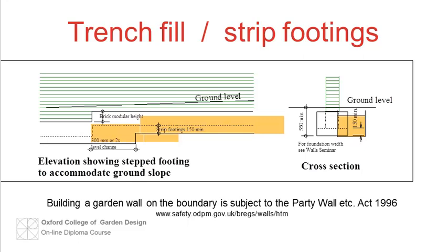The rule of thumb widths for concrete footings are given in the seminar on walls. Remember to take specialist advice if, for instance, the ground is clay, which may contain sulfates. The depth of footing to the underside should not be less than 550 millimeters and may need to be considerably more where there is fill or large depths of topsoil.